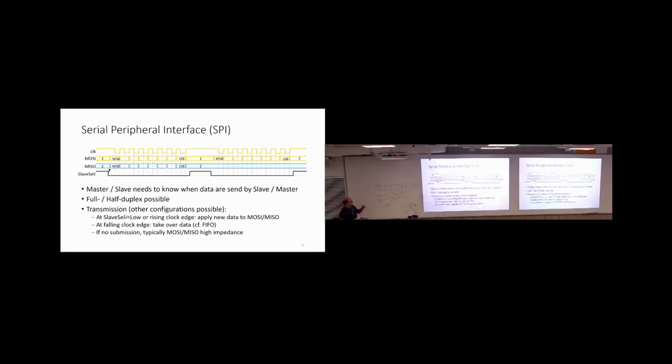You can have this, by the way, also in some, let's call it semi-parallel interface. Yeah? So there is something called quad SPI, where you have one specific message over the SPI to configure the system, and then you reuse the select signals as data signals, and you can transfer 4-bit in parallel. That's quad SPI. Okay.